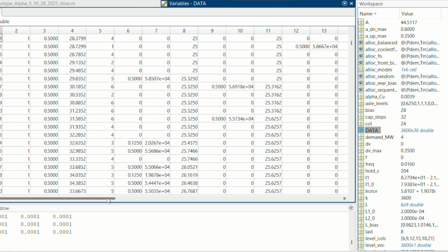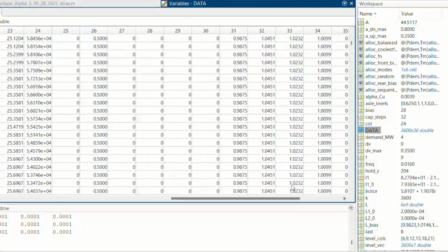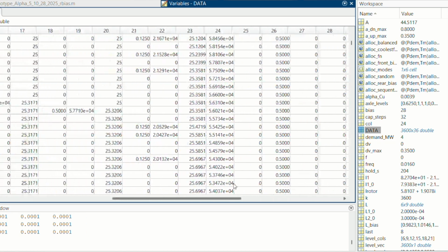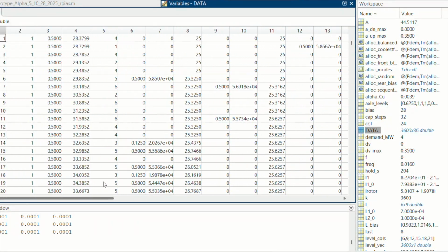Across all of these, one constraint never changed. The train always sees the total power the operator requested. We only change how that power is shared between motors. Running these controllers in simulation, we found that a non-uniform power split can reduce internal drivetrain losses compared with equal split. Among the 5 methods, the physics-informed neural network stood out.